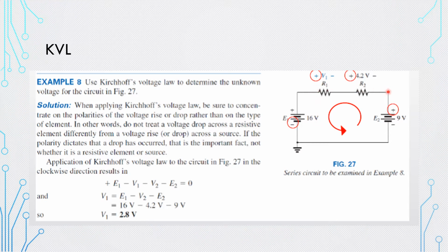For the resistor, follow the first power supply or voltage source with the resistor. So positive is connected with this element in this direction, so this should be positive. Most of the time I go with the highest voltage source. That's why I'm gonna force the voltage R1 to be positive here, negative here, and we're gonna follow the same as the previous resistor. So this is the way how to assign the voltage if it is not assigned for you.